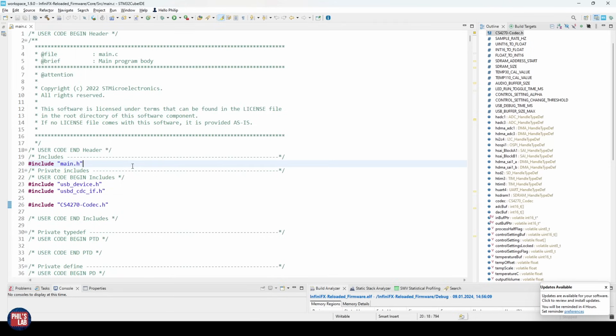Effectively, this is just an I2S feed through. So we take in the data via an I2S stream, we do pretty much no processing, and then we just send it out back to the DAC, because we want to measure the baseline, for example, noise performance, distortion performance, maximum signal levels, and so on.